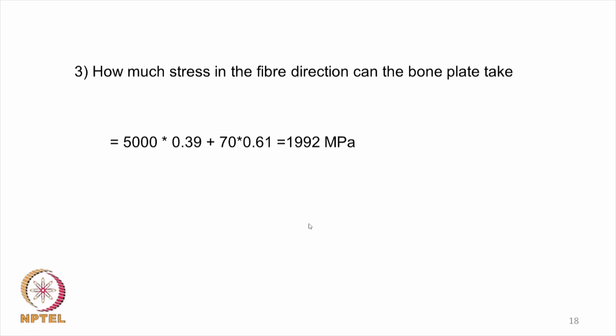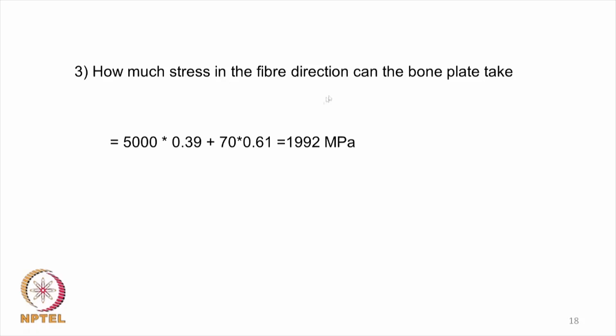But of course, you need to consider that the fibers are all aligned in the same direction as your bone plate, but in reality some of the fibers may not be aligned. So, they will not be able to take in the same force. Only the fraction that is aligned will take in the force, whereas those that are not aligned will take in much lesser force, okay. So, in reality the stress the composite may take in may be much lesser than this. This could be the best case scenario, okay.